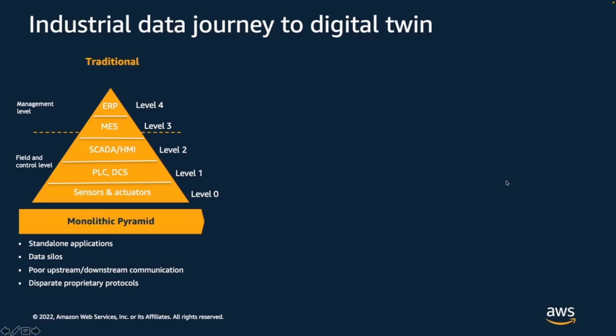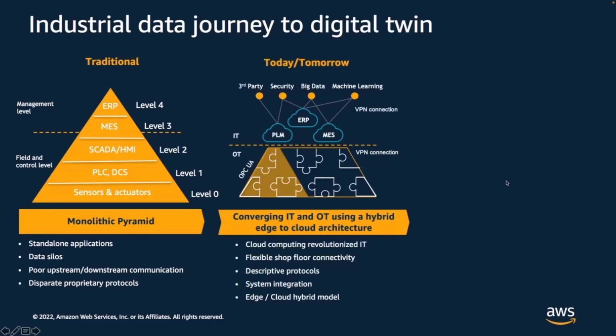The traditional ISA 95 architecture is evolving in a significant way when it comes to IT/OT convergence of Industry 4.0 using an edge-to-cloud hybrid architecture. Because of the latency and availability characteristics, it is not recommended to take a dependency on remote resources for level 0 and 1 systems that you are already familiar with. Critical level 2 systems should also be local, but you can augment additional remote monitoring capabilities so that operations staff can observe global trends. Now, it is recommended that data delays and gaps for this enhanced monitoring capability remotely should not cause any downtime to your production.